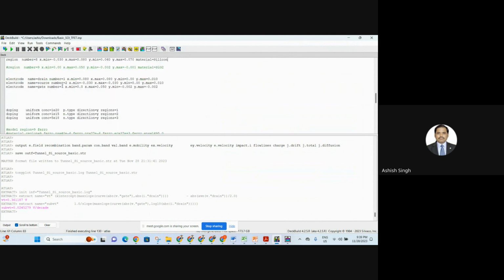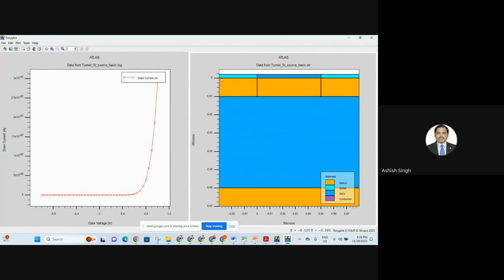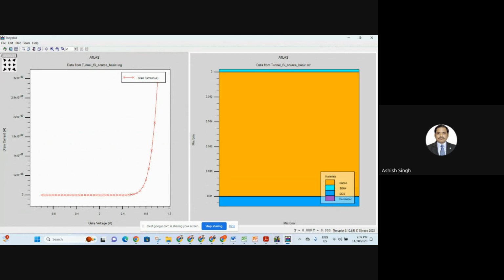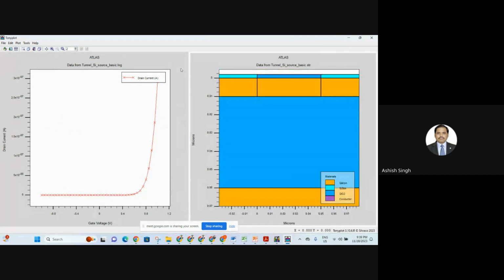Then I have also told you about the electrodes. Electrode means, for example, the source electrode. You can put the electrode on this side, or on the upper side, here at minus 32, 0. The electrode thickness is 0, and the length is, sorry, minus 30 to 0. But the thickness will be very small, meaning no thickness is required.